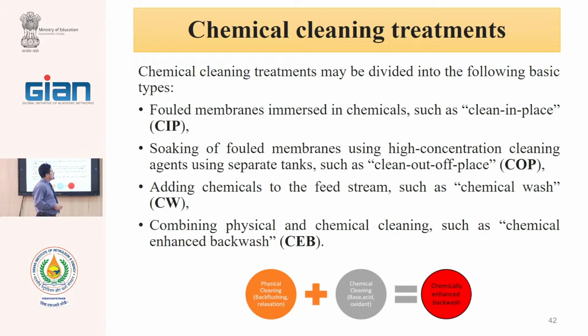We have 2 types of cleaning: clean in place and clean out of place. Most of cleaning is cleaning in place. That means we do not remove the module from the pressure vessel. Only instead of feed, we insert the cleaning agent. Or in the backwash, we insert from the permeate side. Therefore, clean in place, that's mainly CIP,